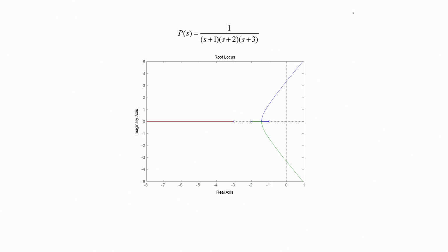Here we shall expect the closed loop pole P_CL0 to be at minus 3 plus 3j and its complex conjugate P_CL0 bar to be minus 3 minus 3j. So, in this complex plane, if I were to represent minus 3 plus 3j, it would be somewhere here.